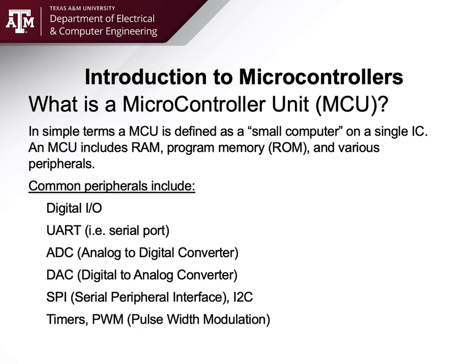So that period is a set time, and depending on how much time it is on, if you have 1,000 hertz, you have a 1 millisecond period. If you did half a millisecond on, or 500 microseconds on, and 500 microseconds off, that would be 50%.